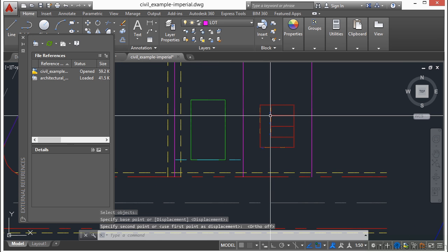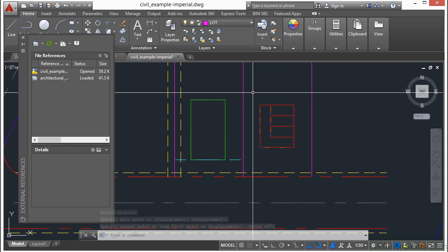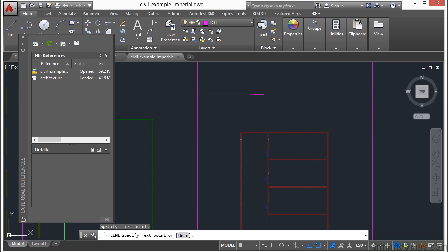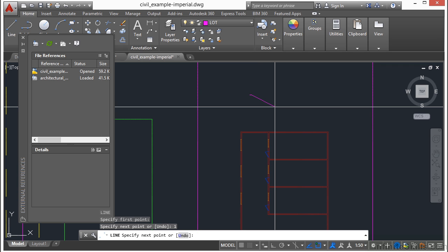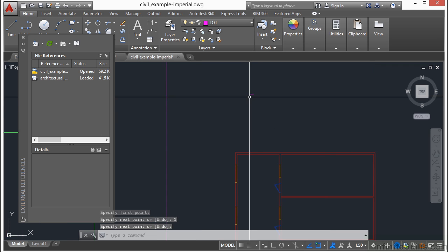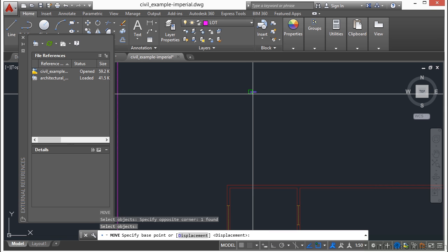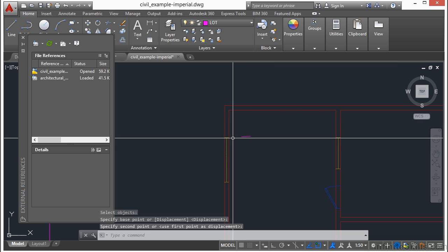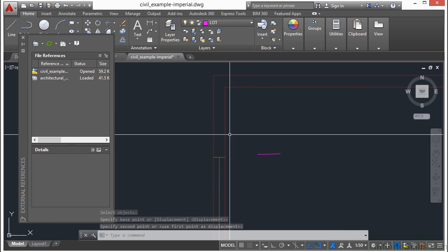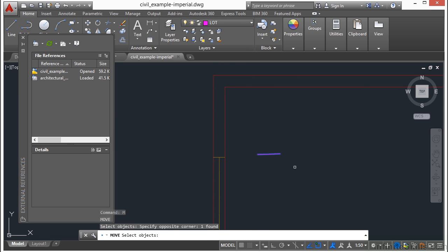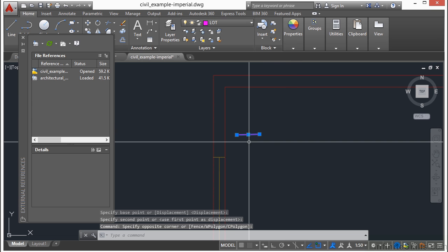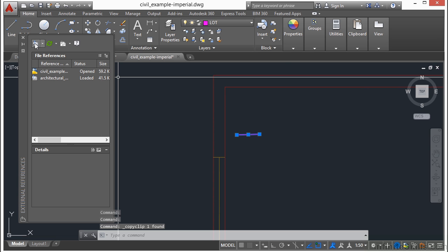Now, AutoCAD knows that whenever I draw something 1 unit long here, as an example, I'm just going to draw a line, type in 1. And it is 1 unit long. Now we see here that this item in comparison, this is 1 foot long. That looks about right. This wall is about 1/2 foot. So that line should be about twice as long as that wall is wide. If I select it here, press Control-C to copy that object.